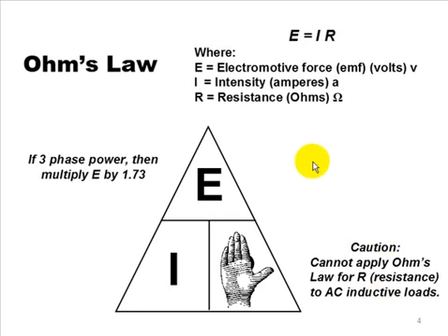Because if you take any motor on your shelf, doesn't matter whether it's PSC or whatever, and read the volts times amps and do the math, and then put your ohm meter across the windings of that motor, it's going to come out nowhere near what Ohm's law says, because your ohm meter has a battery in it.